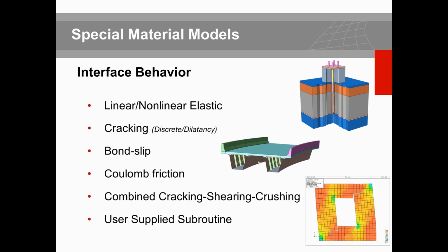This CSC is one of the famous material models that we have, developed based on the initial work of Professor Lourenço for modeling mortar material. And this one can now also be used for 3D, and literally you can model the discrete approach of your masonry structure by using this type of interface representing your mortars and joints.